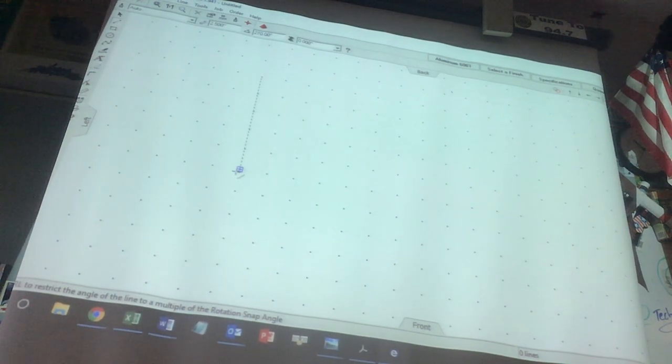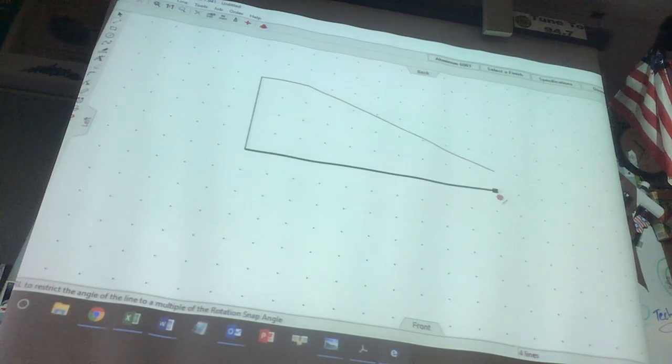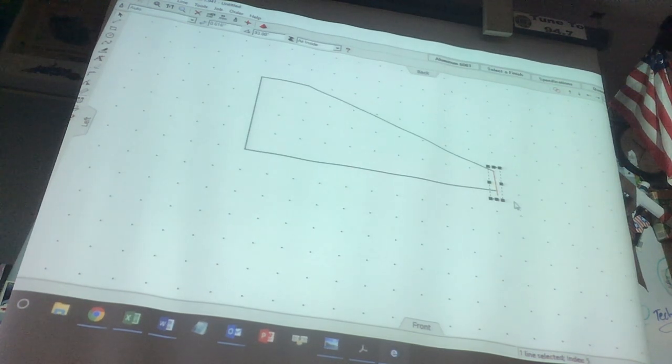I'm going to make this 2.5 inches tall. Let's go 2.5, right about there. 5 inches long. That's about 4, 5's about there. Boom. And that one over to there. And this is actually the first drawing out of the book. If I press the shift key, it'll automatically straighten, because that line got a little bit messed up, as you can see.